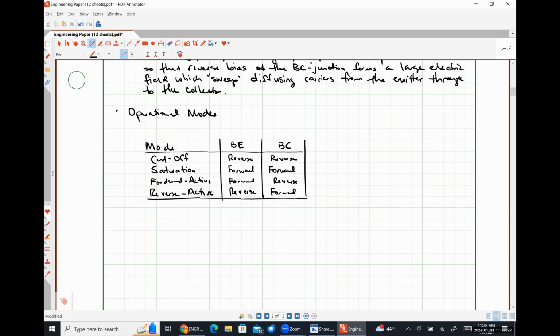So realistically, we never actually operate the device in reverse active region on purpose. It will behave as if it is in the forward active region. It just gets really hot doing so because it needs that extra energy in order to have enough charge carriers pass through things.